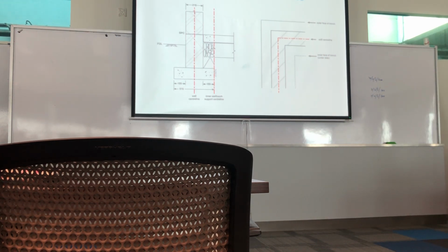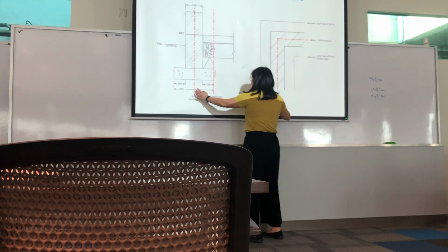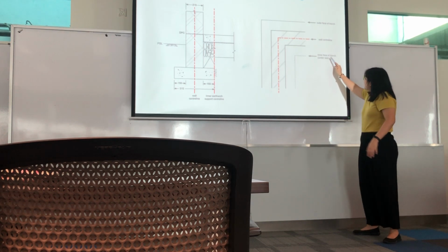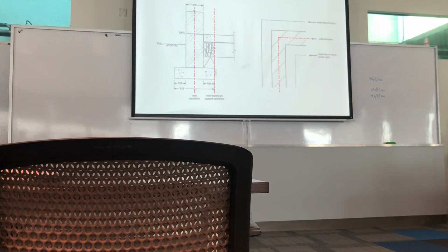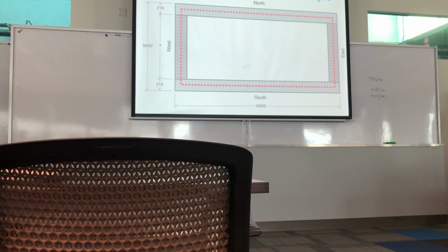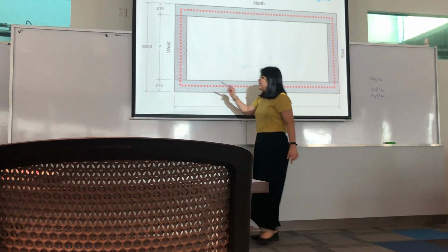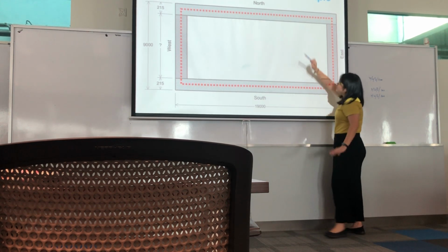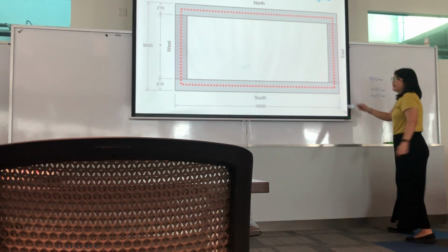If you look at the plan, this is your center line, which is this, right? Now you want to know the internal length, internal face. What is the perimeter like? So if I show you an overall picture, just now you have this one, center line. Now I want to know what is the length of this one, the perimeter, the curve of the internal line. So you don't need to measure, you just need to do adjustment based on the center line.